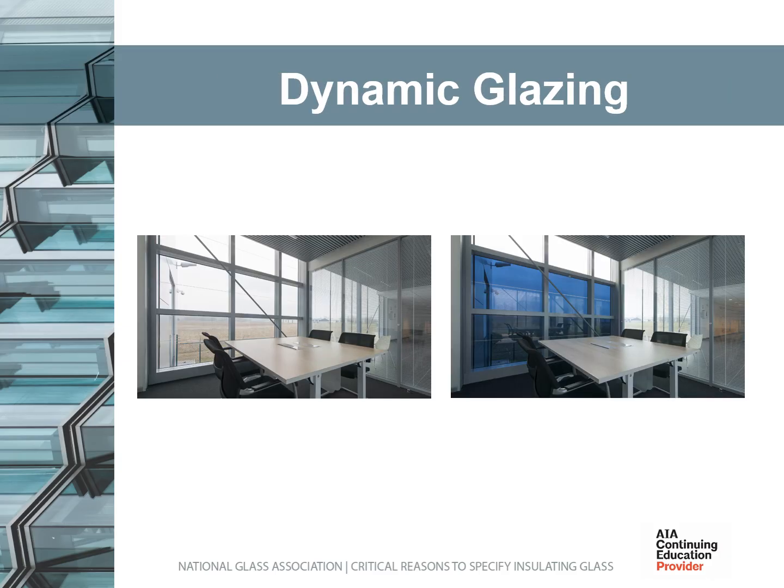One of the significant advantages of dynamic glazing is the ability to change the glazing properties based on environmental conditions outside. These photos demonstrate capabilities of dynamic glazing to adjust visible light transmission, or glare, to provide optimal daylighting conditions. In the photo on the left, the dynamic glazing is highly transparent on a cloudy day, while in the photo on the right, the same glazing is tinted on a bright sunny day to minimize glare and control solar heat gain. These photos are courtesy of Sage Electrochromics.